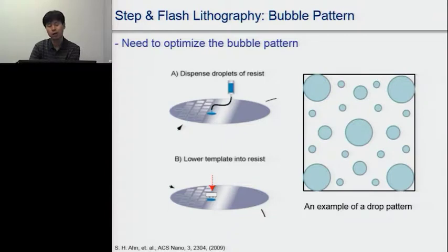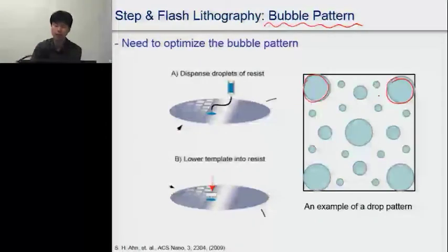For this process, the bubble pattern formation is very important. The bubble pattern formation means deciding the distribution of the resist drops, and also deciding the volume of each individual resist drop.